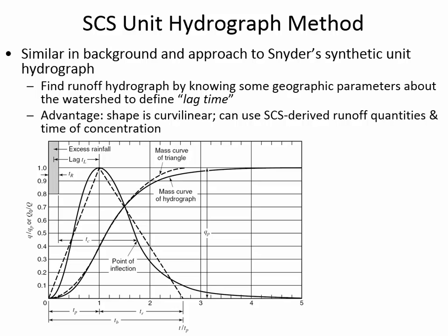And so the advantage of doing this is they found through a lot of research that many watersheds have a similar shape of a hydrograph, meaning that it comes to the peak more quickly at the beginning of the storm than that peak tapers back down to the base flow. And so that's the common thing among all watersheds, is that the peak comes more quickly than it goes. Sometimes the time to peak is just a matter of minutes. Sometimes the time of peak may be several hours.